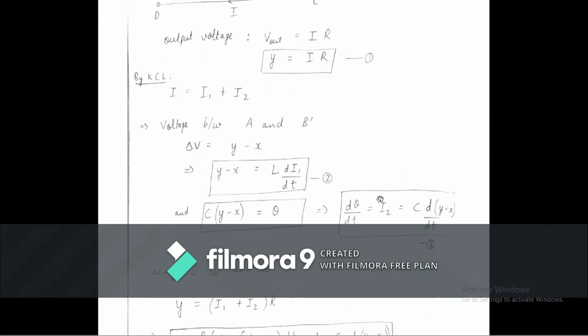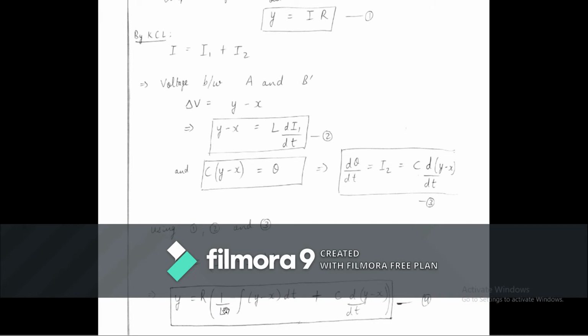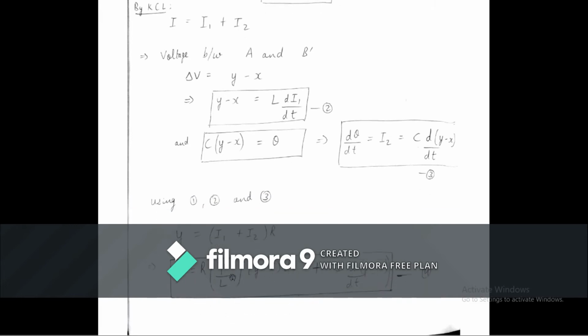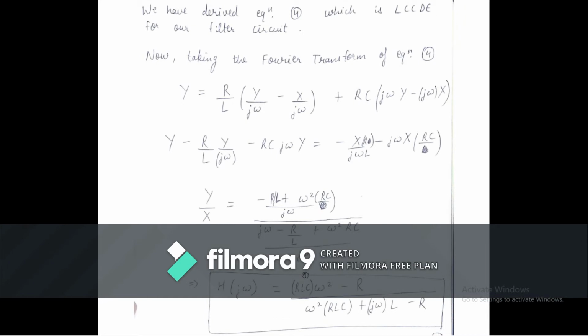Now using equations 1, 2 and 3 in this equation, we get y equal to (I1 plus I2) R, and we simplify this equation to get this equation. This is basically our LCCDE for this filter. Now we will take the Fourier transform and the Laplace transform of this equation to get the frequency response and transfer function.